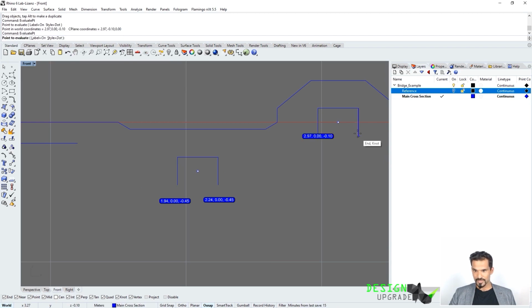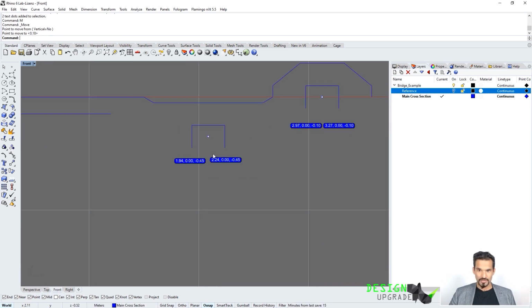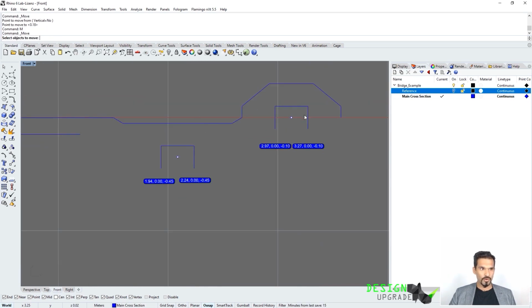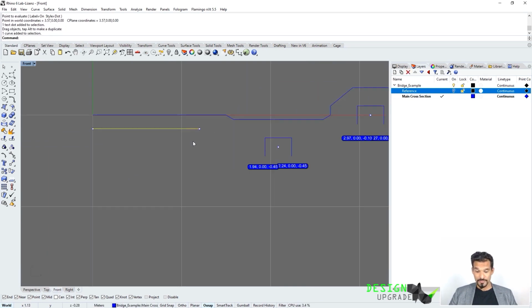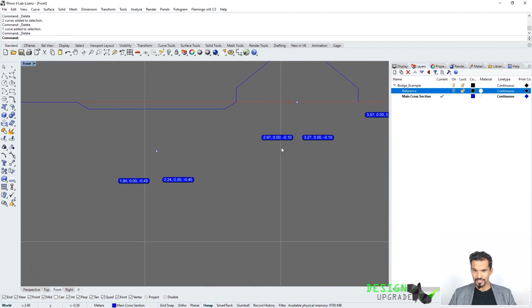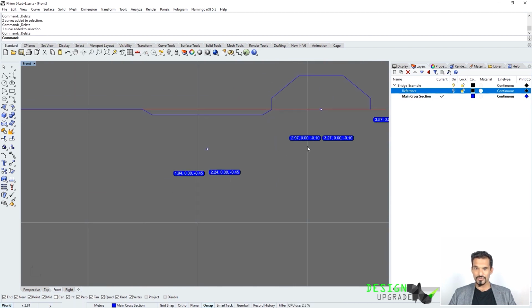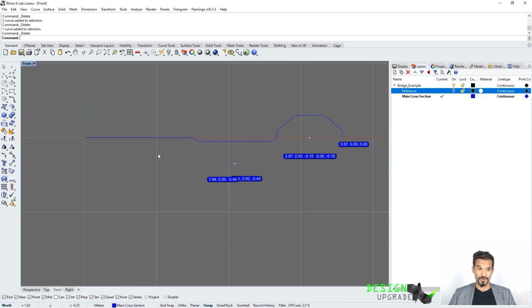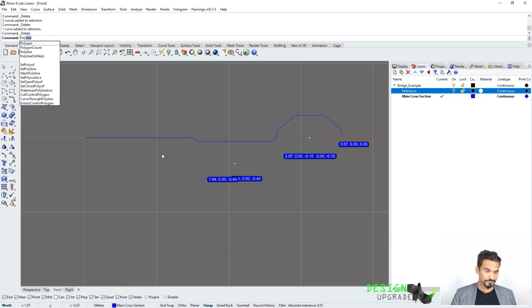So I'm just going to do that and that, take those two points and move them down. Just do one more here. Yeah. The interesting thing is now that we can rebuild this polyline just by means of using those coordinate systems. So that is kind of nice because I can now delete this information that I have here, right? And just based on this coordinate system, I'm going to try to model up this polyline that we have just drawn. So just again, do a polyline.